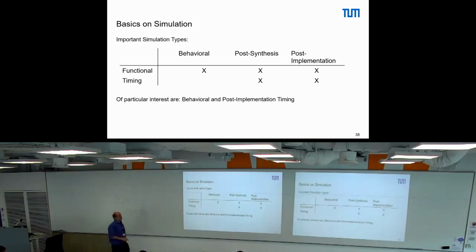And for this we need to place and route our circuit. That is why we have a better model than here, right? So we can have a rough estimate for this delay, but we can only give a worst case or some educated guess from the fab that is included in some synthesis, but no precise timings. Usually what is done is that there is some worst case estimate.